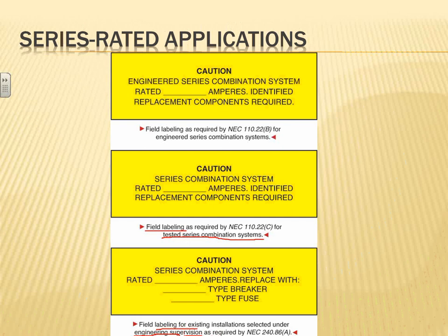Current limiting fuses have been challenged by plan reviewers. One of the reasons we don't use fuses is because we can never prove to any plan reviewer what the actual let-through is. They won't allow the use of the graphical method in any plan review. So that's what this considered.